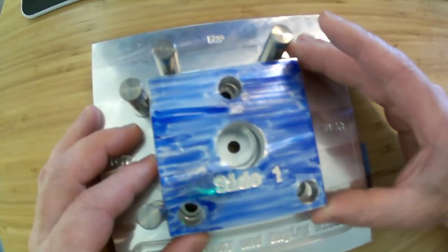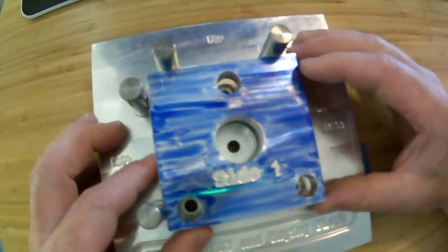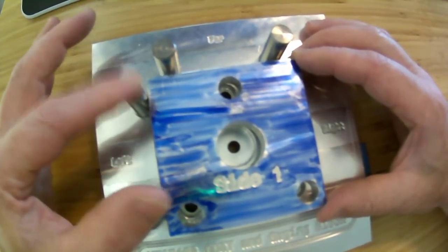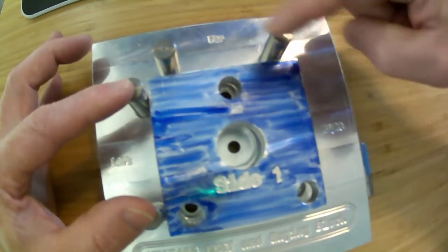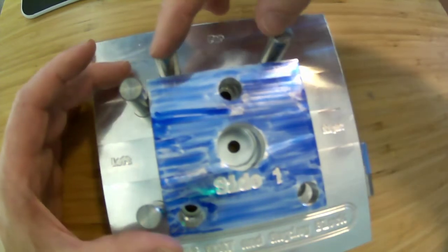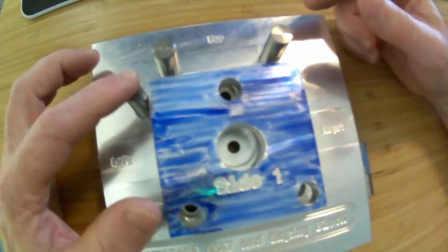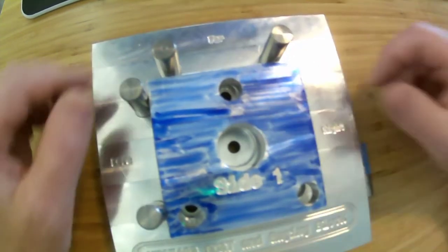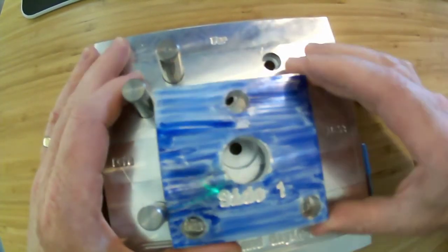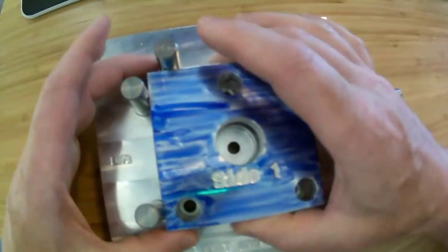And so in actuality, this will not be deterministic anymore, because either the part will line up with these 2, contact these 2 sides, and then contact one or the other of these pins, or the part will contact these 2 pins and then contact one or the other of these 2. But it can't contact all 4 at the same time because I've eliminated some on the bottom. And so I can take out a pin. Okay, so now I have 3 on the bottom, 2 on the side, and 1 on the edge.